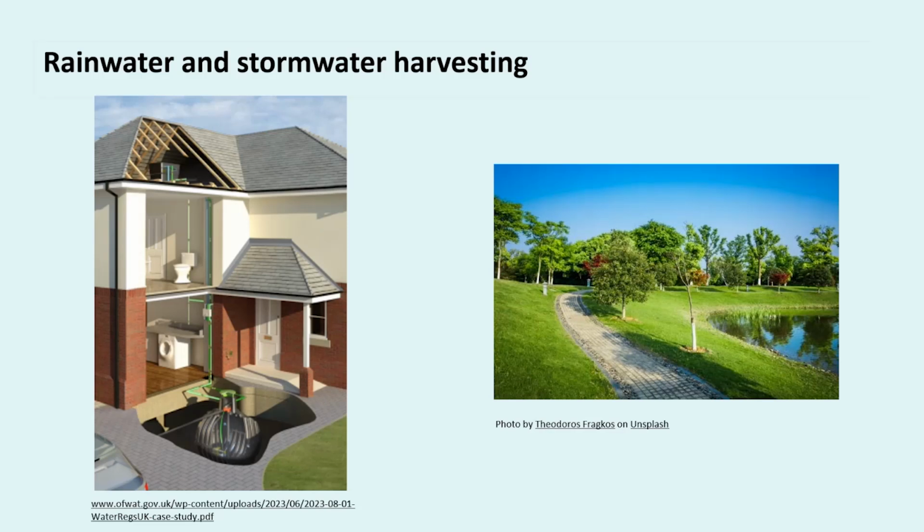An alternative approach is actually stormwater harvesting. That differs from rainwater harvesting because it captures and reuses water that drains from other impermeable areas in the development, such as roads, footpaths, and landscape areas, and can also take the roof runoff as well. So the larger collection area generates larger volumes of water, obviously, which requires more storage, but also means that stormwater harvesting may be better suited than rainwater harvesting in areas with low or less consistent rainfall.